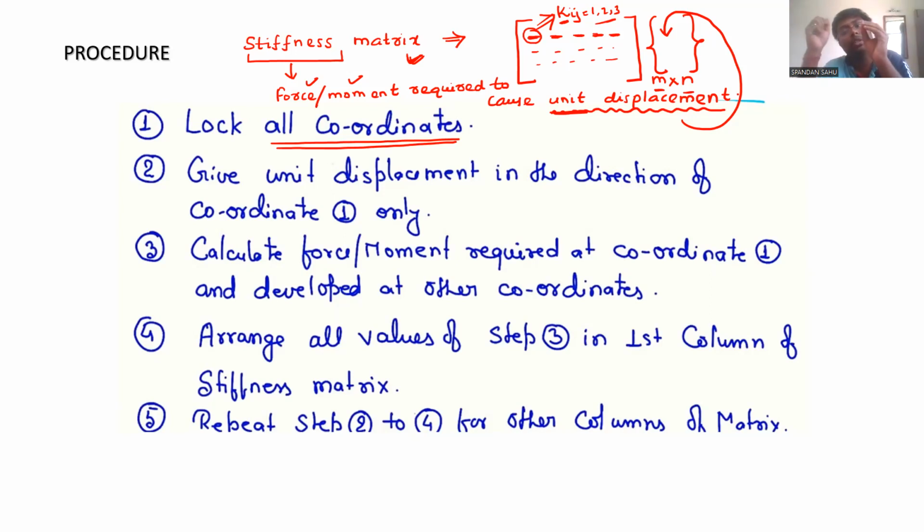After getting those displacement at those joints or the points under consideration, we are applying one redundant which is unity in nature at a time, removing the external load, and by applying some compatibility condition at that joint, we are writing our equation and solving the unknowns.